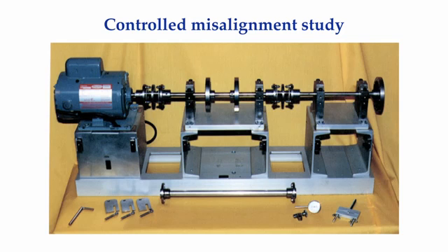At the beginning of this tutorial, I asked the question, what will happen if you misalign a drive system? Will the vibration go up, go down, or stay the same? The vast majority of people I asked that question to say that the vibration will go up. Their reasoning, I guess, is that by misaligning the shafts, you are putting a problem into the machine, and therefore the vibration must go up when problems are present.